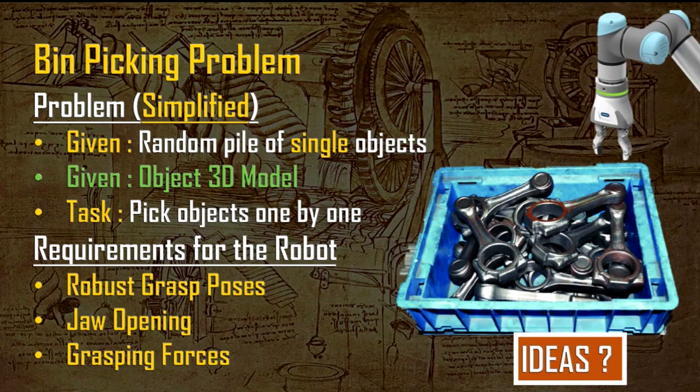In applications where bin picking is not there and everything is assorted on the same level, you can still use 3D depth images to identify not just the position and location, but also how the object is oriented in the 3D space, which can be estimated easily with 3D images.